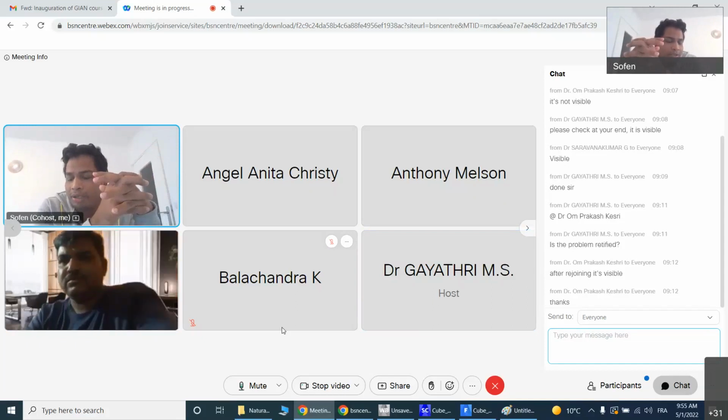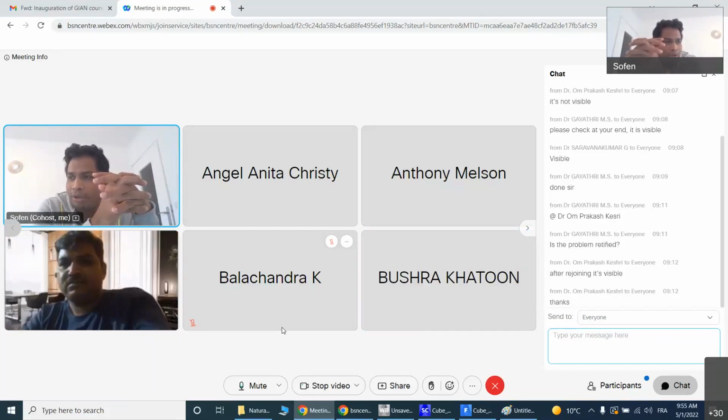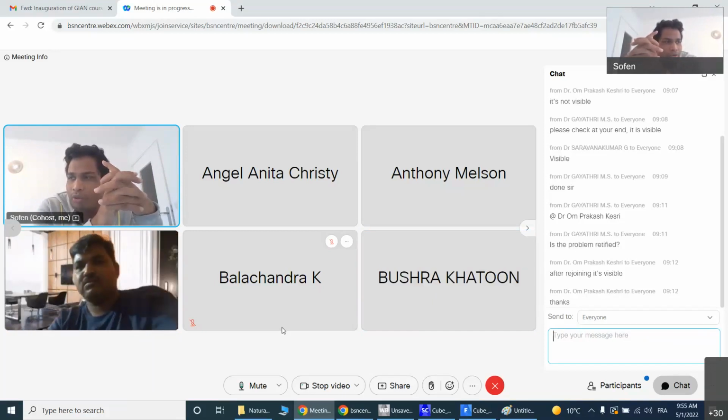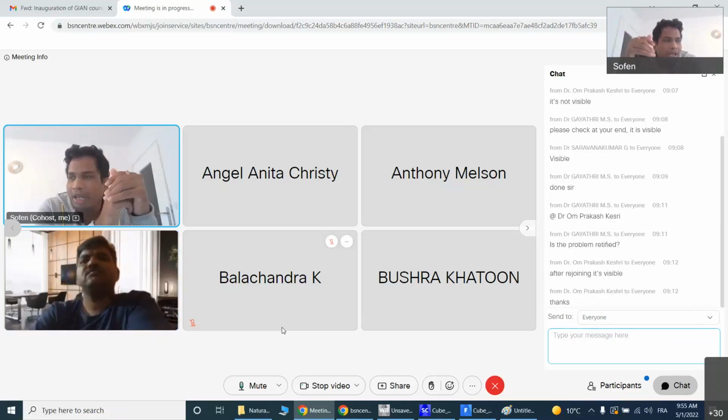As a rough estimate for Fluent, you need around 1 to 1.2 GB of RAM for each 1 million mesh cells. Suppose you have a cavity having 4 million mesh cells, you need around 6 GB of RAM dedicated to Ansys for the computation.